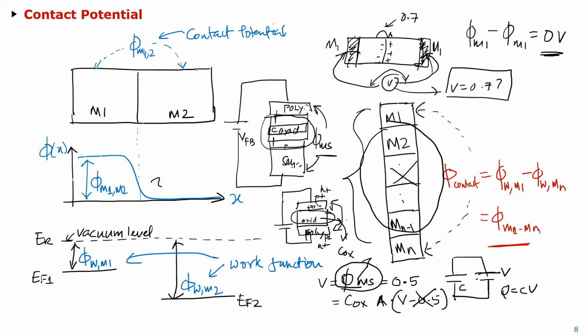Yeah, so I became confused with this thing. I was thinking this built-in potential is directly related to the capacitance. No, no, that's not it. The capacitance still appears as it is, just that because you have two different materials, if you just had two metals or two P plus or two N plus, then you'd see the capacitance right away. Whereas if you have different materials, you have to first overcome that work function before you can have the electric field in that capacitance come through.